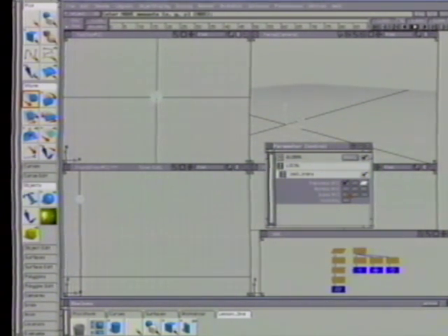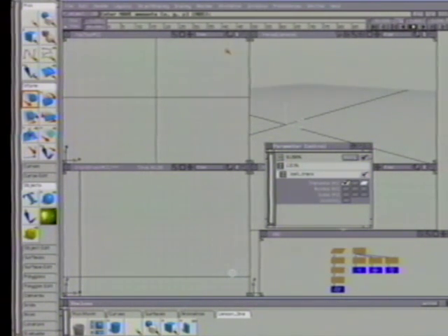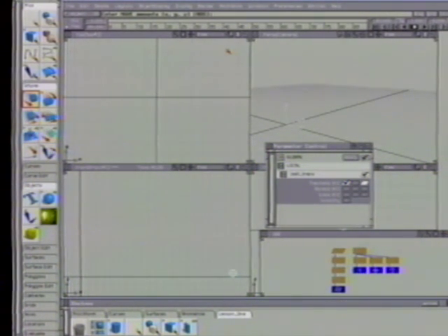Click in the Parameter Control window, turn off the Z Translate, and turn on the X Translate. With Ball Trans still active, select Set Keyframe. In the time slider, go to frame 90. Select X-Form Move and enter 20 to move the ball in the X direction. This will represent the range of the movement forward. Select Set Keyframe. The Ball Trans node will now move between 0 to 20 in the X direction over 90 frames.